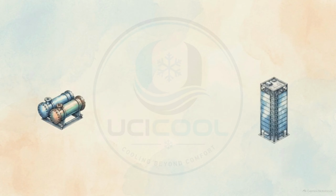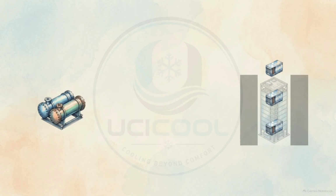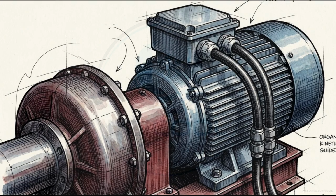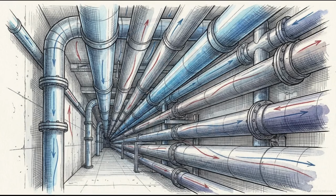Large-scale HVAC systems operate on a massive physical disconnect. A centralized chiller plant generates immense thermal capacity, but that cooling power is physically isolated from the loads distributed across the building. Bridging that gap requires an active transport layer, the chilled water pump. Its core function is converting electrical energy into the fluid velocity and pressure required to physically move that thermal mass through a complex network of piping.